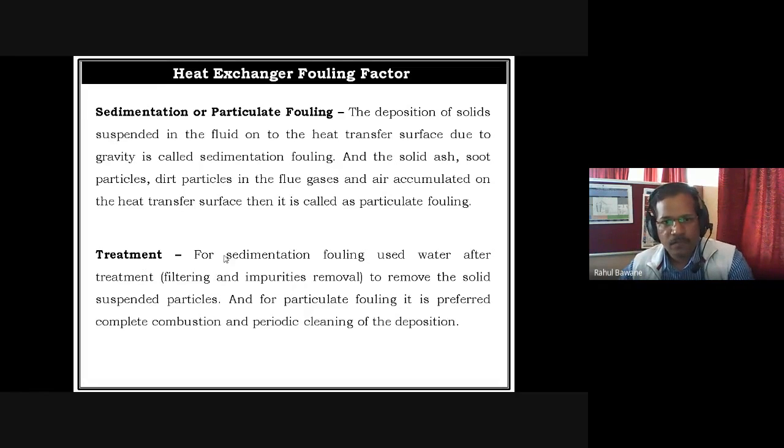Treatment for sedimentation fouling: use water after treatment. That means filtering and impurity removal. Whenever you are using such a system, always use water after filter. That means there must be a water filter before entering your heat exchanger. That filter will remove the solid suspended particles. And for particulate fouling, that is carbon deposition, it is preferable